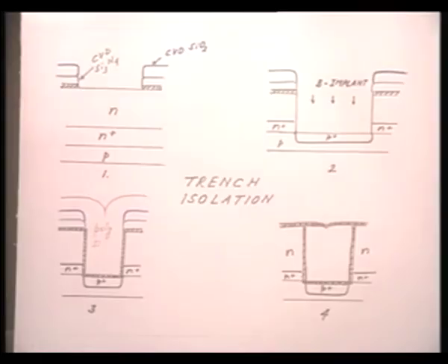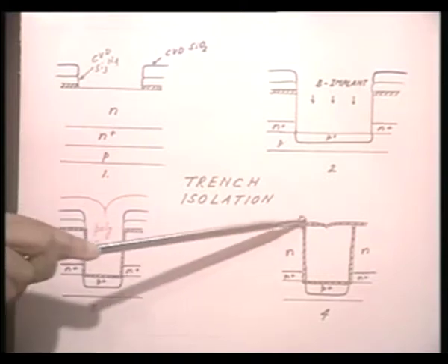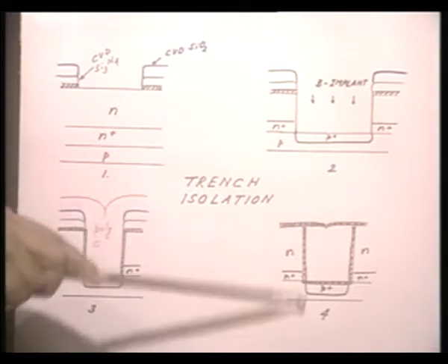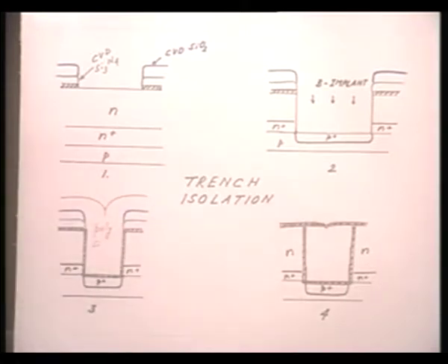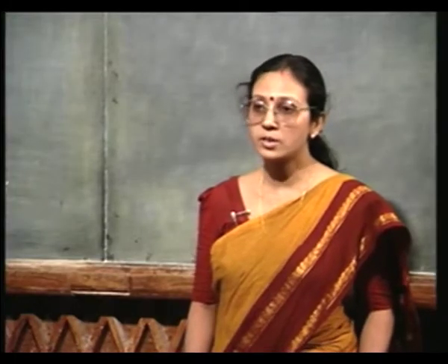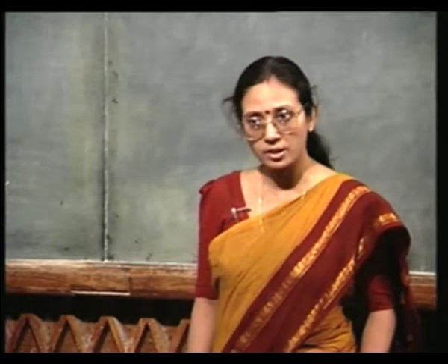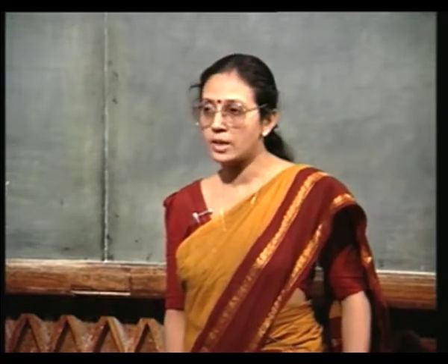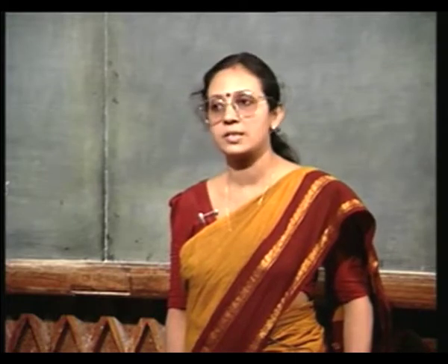And finally, this thin oxidation. You need this thin oxide because you want to seal the polysilicon on all sides. Undoped polysilicon is not going to conduct, but unless it is sealed on all sides by silicon dioxide, you cannot be perfectly sure of electrical isolation. Silicon dioxide is a much better insulator, right. So, I need to have silicon dioxide on all sides.